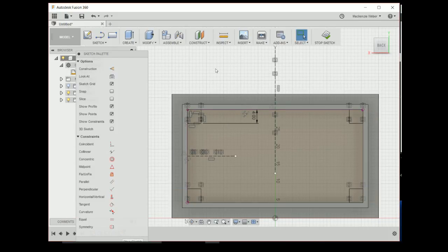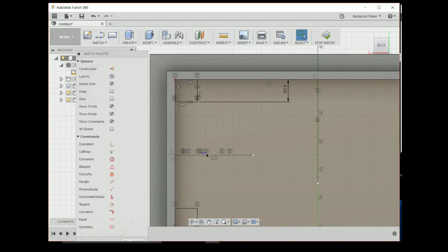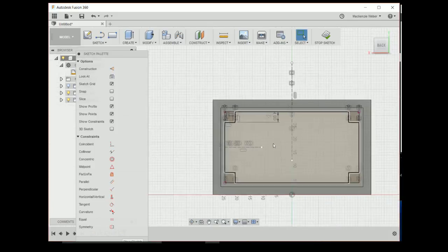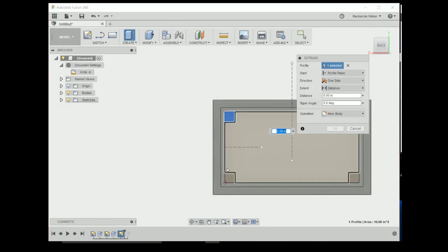It will allow you to create relations like that, and creating objects based off of each other like that will really simplify a lot of things. If you need to change things in the future, you might only have to move one thing around, and it will move all the other things the way you want them to. But now we have all this mess of relations here. That's not really a problem, though. I'm going to try one other thing here. No, never mind. Alright. So here we can create extrude and click on these 4.